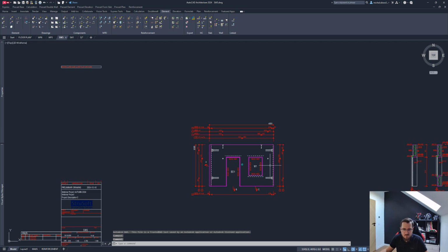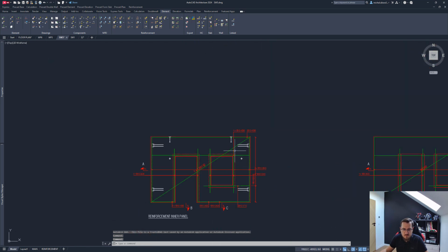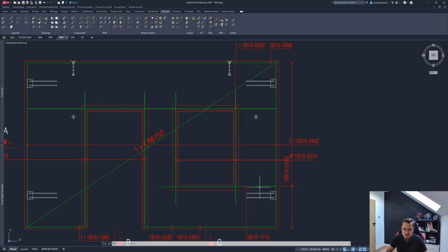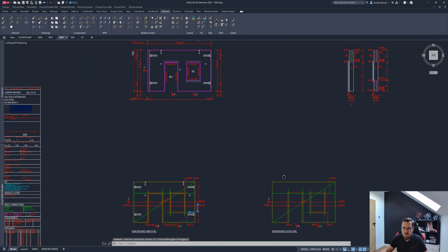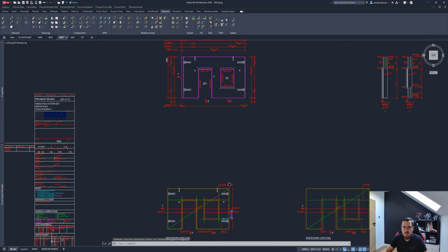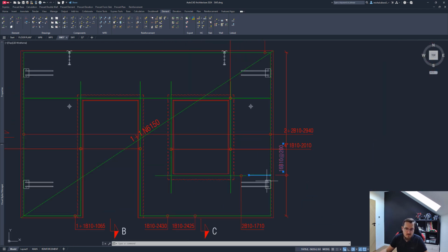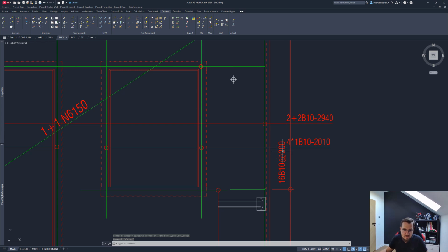All right, so here we have a bunch of stuff. Immediately on the drawing, there's some reinforcement that's shown. There are custom materials that were placed in that wall automatically while we were creating connections, and we also have that edge reinforcement that's been created, right? We can convert that to a reinforcement group, or we can leave it as is, as 16 B10 bars at 20. So we specified that distance, 20 centimeters, 200 mil.